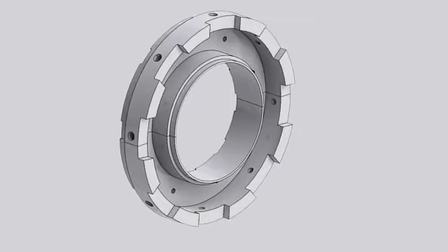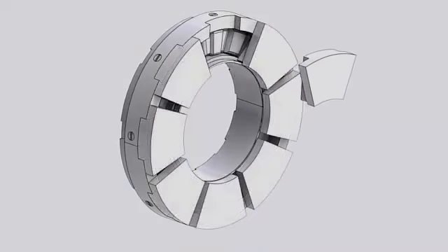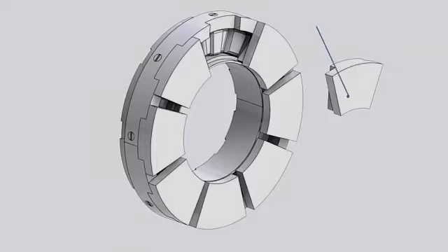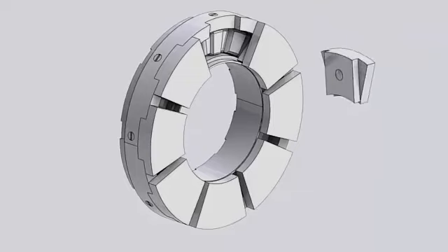The base ring provides support for all parts of the bearing assembly and keeps parts in the proper location. The pads are shaped like a sector of a ring. The bearing surface is covered with Babbitt alloy. Every pad has a hardened steel button on its back called the pad support. This pad support allows the pad to tilt slightly in any direction.